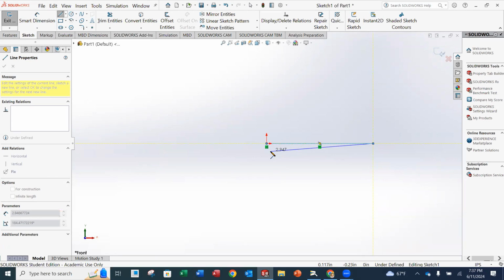So a coincident relation, that means that that first point is coincident with the origin of our part here. Additionally, you're going to see this horizontal green line there if you got the horizontal in there, okay? And what that means is that's called a horizontal relation, so that we know that that line is horizontal and it's not slightly up or down, okay?